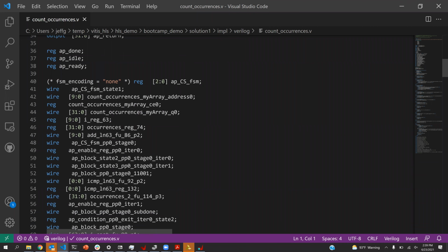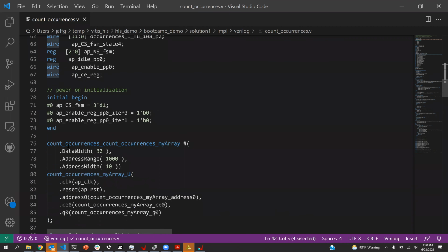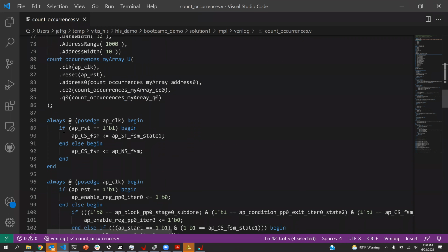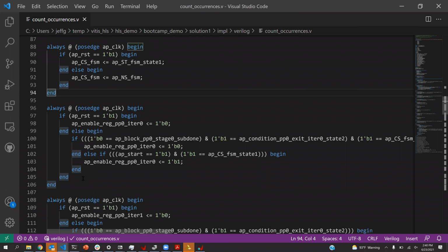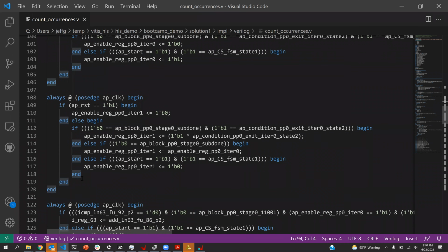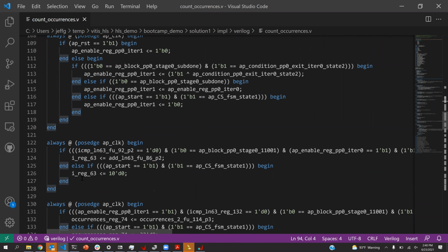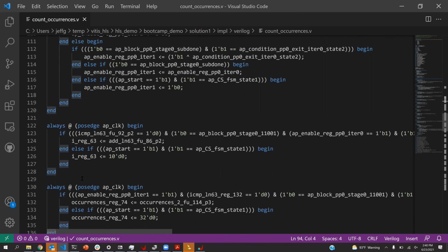And let's see this beautiful Verilog that we've written. Does this look familiar? You've got a current state register. Sorry, I know most of your SystemVerilog you used logic, but in Verilog we use reg or wire. It doesn't really matter. Hey, look, you've written code like this. If I reset it, go back to state 1. Otherwise, current state equals next state. And then next block. Next block. I don't know what all these things do.